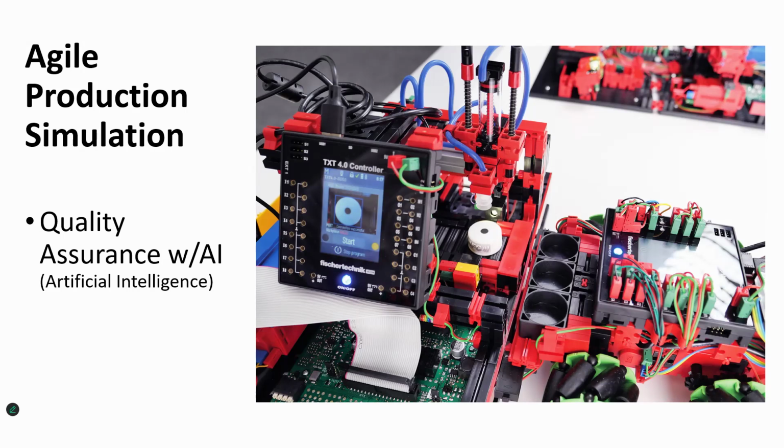It also has various fault patterns. And again, all this gets classified using the trained AI. Depending upon the color, the feature, and the fault pattern, in this case the workpieces are not sorted into separate bins as they were before, but the workpiece either gets placed back onto the AGV as an acceptable, good-to-go workpiece, or it's put into a reject container, meaning that it's not okay or defective.